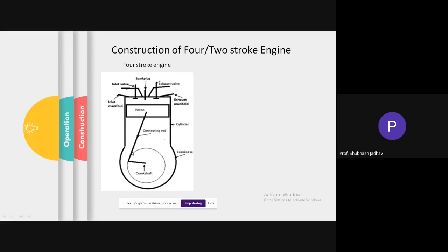And this is your piston, this is your connecting rod, this is your crankshaft with the offset distance shown here, which we call the crank. The part which is covering the crank is called a crankcase. The lower part where we have some oil is called a sump. The upper part is called a cylinder head. This part is called a cylinder, and here the cover will be there. So tappet cover and everything will be there. On the upper side of the valve there will be the rockers, and the covering of that is called the tappet cover. So this is how a four-stroke engine is. In brief, the constructional detail is something like this.